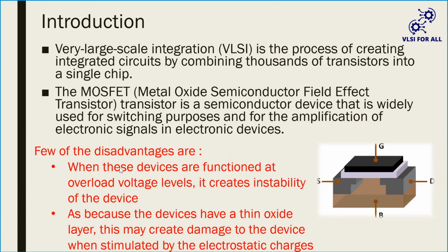So they have some on resistance. In such a case, there will be a huge current flowing from VDD to ground. There will be a path that we call a low impedance path. So during transitions, there will be a current in the circuit and a power dissipation. That power dissipation is called switching power or short circuit power. At length, you can say it is dynamic power.